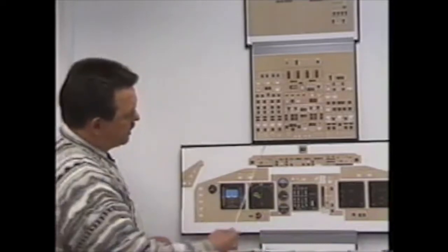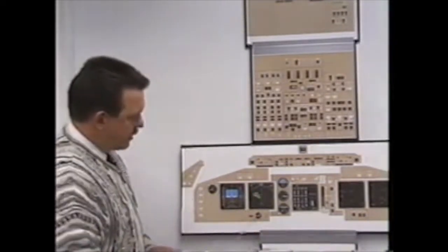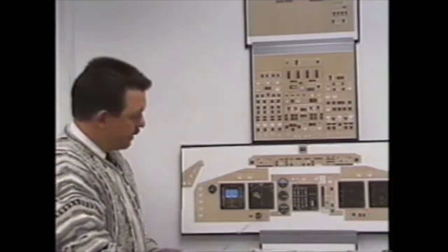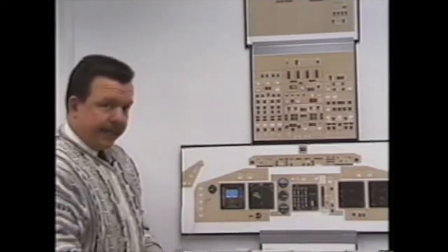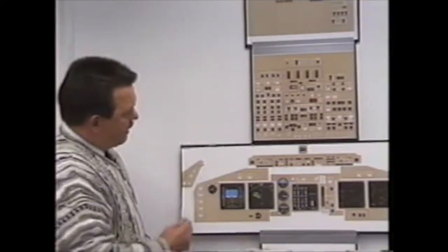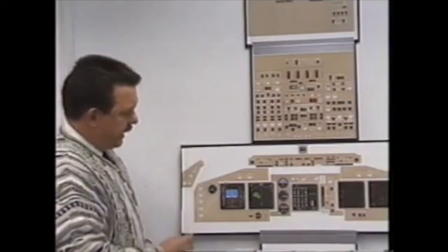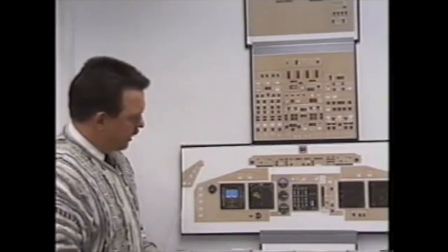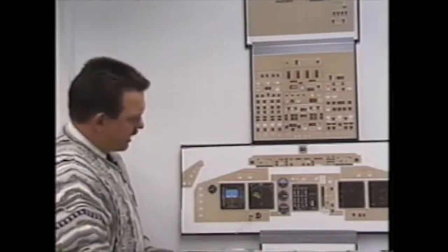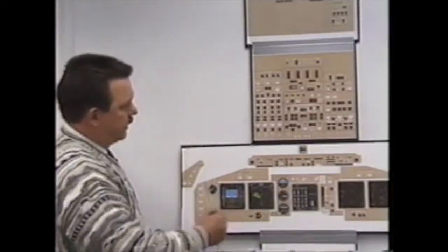The brake accumulator gauge is in System 4. System 2 pressurizes the alternate brakes. As a result, it cannot bring the gauge up. The brake source light is out, though, indicating that brakes are available on hydraulic System 2. I then reach up and pressurize hydraulic System 1. System 1 is pressurized. Again, that will not bring up the brake accumulator gauge. The brake source light is still out, indicating the brakes have gone from 2 over to 1.